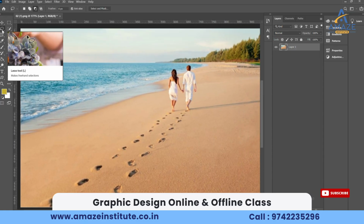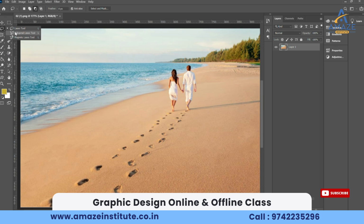Now right click, polygon lasso tool. If you see, now I keep a point here. After keeping a point, like in the pen tool, how we keep a point and drag a line, it comes like a temporary line. After that, if we keep a point, now this point is fixed. Now I'm keeping a point here. Like around 4 points we should keep minimum.